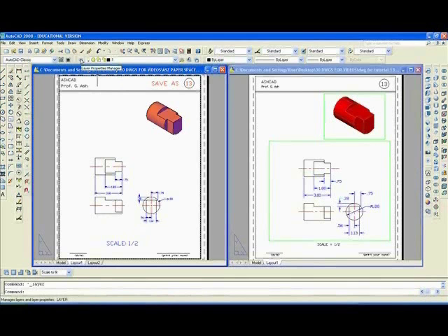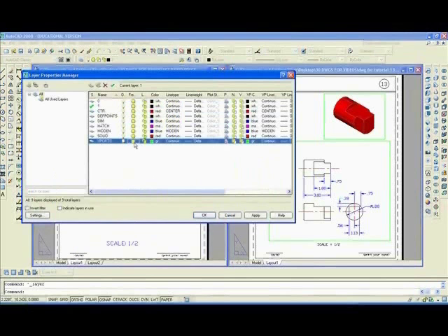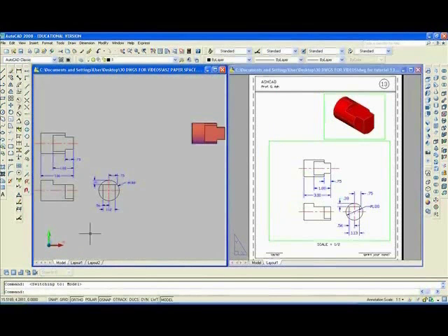Well, one thing I can do is to go back into layers, the viewports layer, double click inside, or even go into model space, doesn't really matter. And I can type DIMSCALE, make it 2, enter.